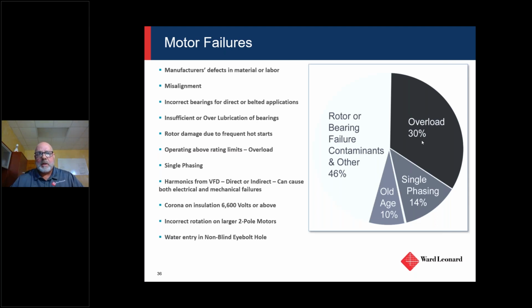They do. The materials for winding and insulating have gotten a whole lot better over time, and I think the longevity has followed that. When Nomex came around, which is the material that we use on our rewinds, you start to look at laminated materials like Mylar or Dacron.